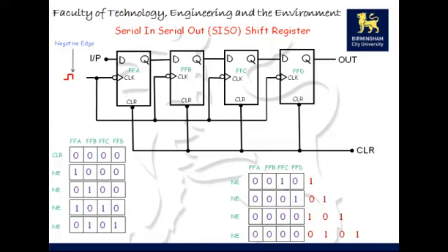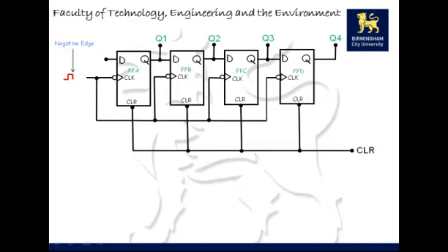You may think, what's the application of this shift register? Well, this particular one, I would say a time delay. We can actually delay by 8 clock pulses the data going in and coming out of the shift register itself. Okay, that's the first configuration. The second one is